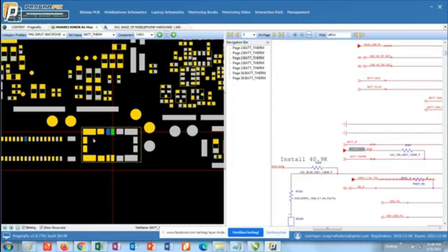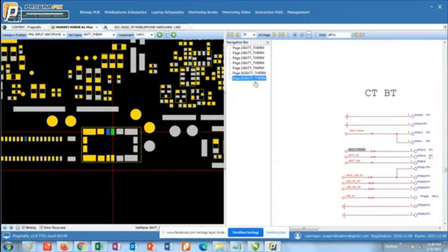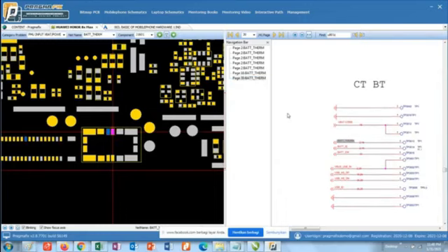So if it does not heat, this connector stays connected to the battery. Because the resistance to the ground goes down when hot, the more it connects, the voltage on the battery temperature line will be lower. The more it is connected to the ground, the potential difference value will drop. So the voltage on this temperature line will fall because it is increasingly connected to the ground.